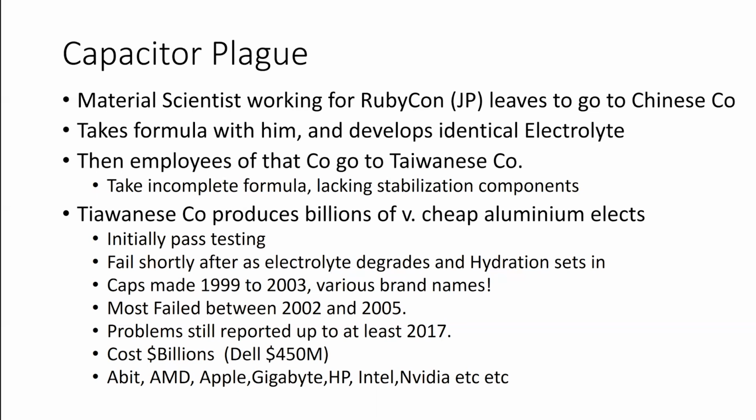And there's now a healthy industry of people recapping electronics. You'll find that in any electronics program where somebody takes an old radio or an old television and starts to fix it, the first thing they do is they recap it. They take all the old capacitors and replace them with modern capacitors. Because apart from electrolytics, there are other issues with tantalum capacitors that can explode, and RFI capacitors that have issues with breaking down. Those are another discussion for another day.